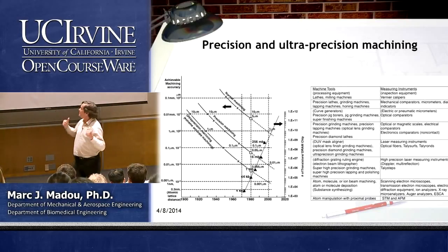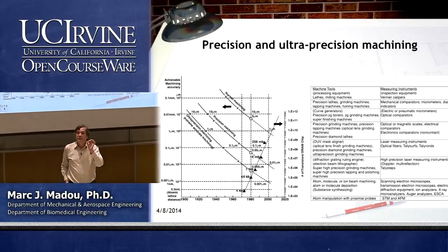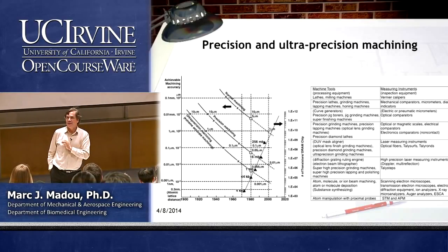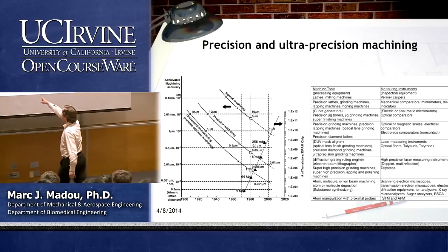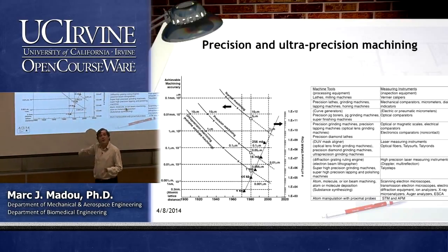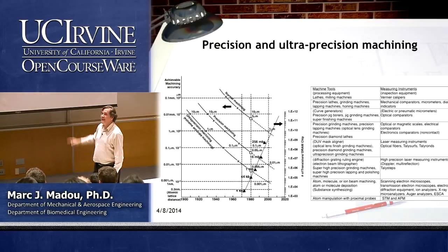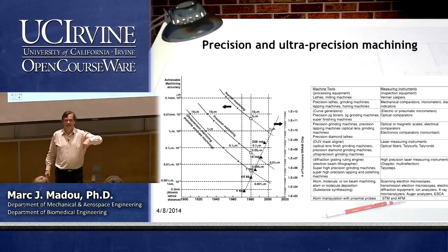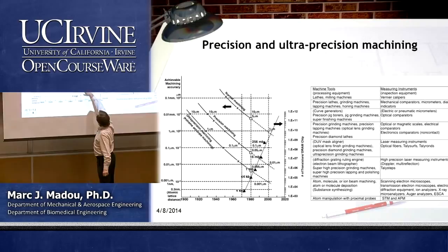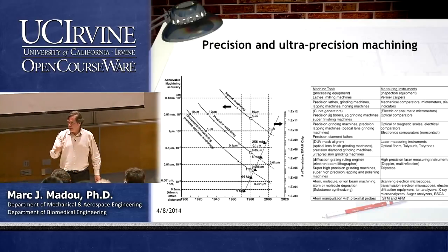And it's common. Now, one more time, the difference between the two. In this case, you can make items with very small absolute sizes, right? Relative tolerance, in this case, is rather poor. Relative tolerance, in this case, is much better. But the absolute size is bigger, right? That was the first point. Now the second point, if you compare these two, what axis are you comparing? These numbers have to do with one axis only. The line describing progress in the integrated circuitry is in all 3 dimensions. I see you nodding. Do you get that?